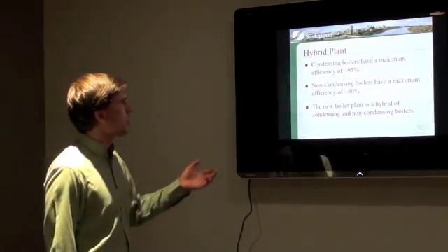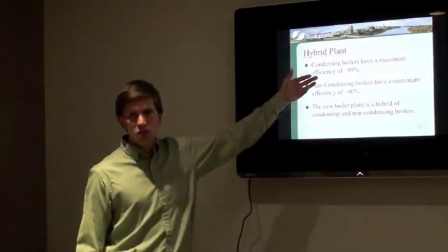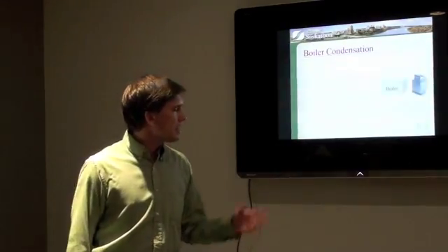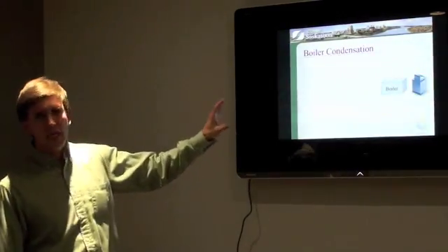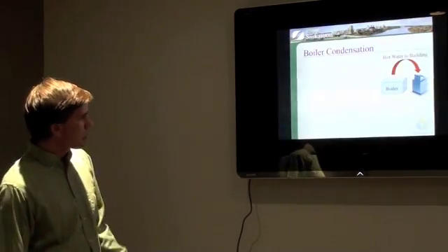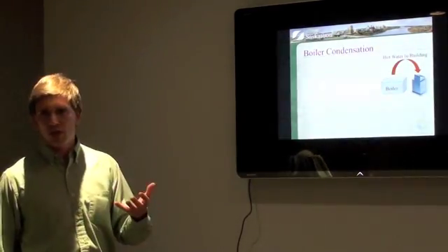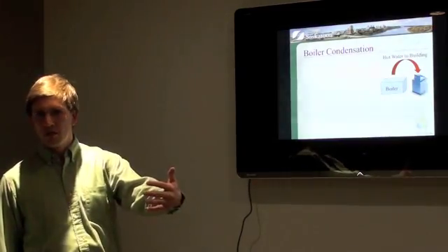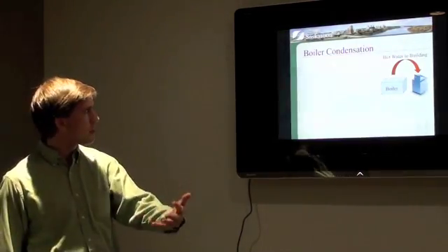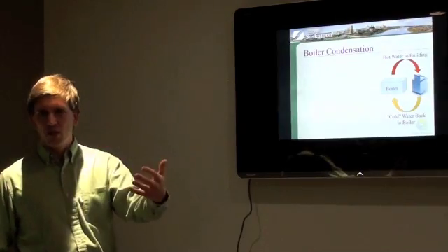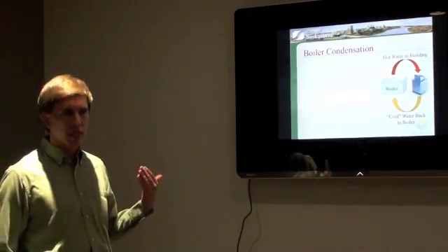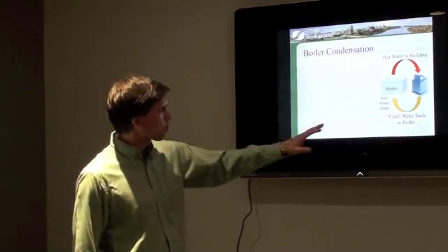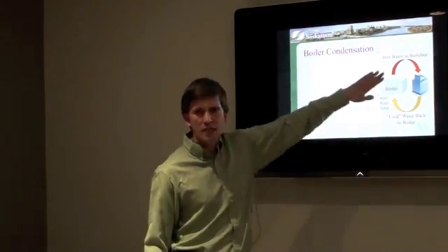Now the question I always get is, if condensing boilers are 95% efficient, why don't we just go with a condensing boiler system? Well, if you look at a facility, you've got a boiler that's trying to heat an airspace in a building. The boiler heats water to a certain temperature. That water goes through some sort of heat exchanger to heat the airspace. When it does that, it gives off a certain amount of energy, and the colder water gets returned. That colder return water is the inlet temperature back to the boiler that it has to heat up again.